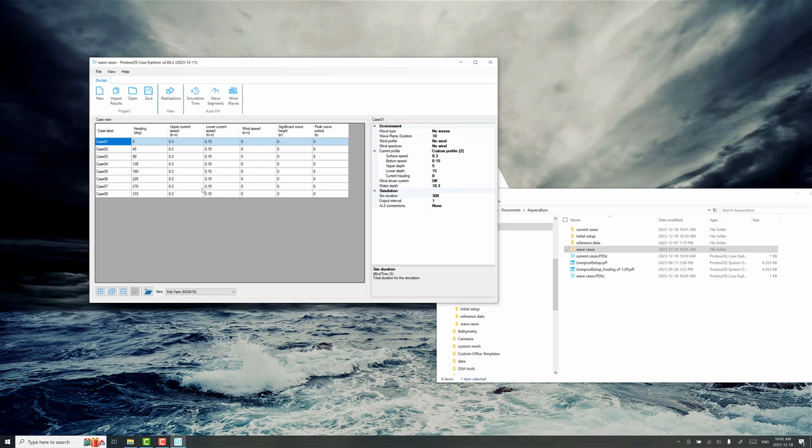Okay, and now what I want to do first is go through and specify all the wave height data that I've got. Now, this is not the real wave height data for this system, it's just representative for the purposes of the tutorial here. Of course, you'll need to have this data for your site. I'm just picking a few values here, with the biggest being 1 meter significant wave height, and then we've got the associated peak periods for each direction here. Just putting in the data. Okay.